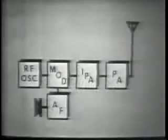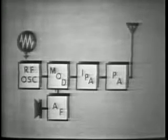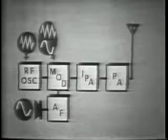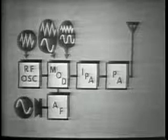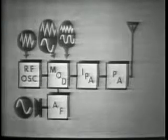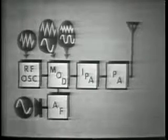Let's summarize our knowledge of conventional amplitude modulation. Now, you know that in an AM transmission, an RF carrier is required, and that for 100% modulation, an audio frequency of equal peak amplitude is needed. When the two frequencies mix, the result is four frequencies: the two originals, the sum, and the difference frequencies, which are called the upper and lower sidebands. When modulating 100%, each sideband voltage is only half as great as the carrier voltage. The audio frequency is not developed in the output because the RF resonant circuits have a very low impedance to audio.